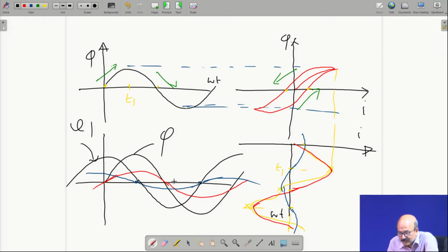One is of course the rate component, which is predominant, which is again lagging V1 by 90 degrees, but you have an in-phase component which is in phase with V1. Why has the in-phase component come up? To account for the hysteresis. V1 multiplied by I1 will be the hysteresis loss on integration. If you do it in time domain, or you just do phasor multiplication, V1 capital and I1, cos of angle theta is 0, cos theta is 1. So V1 I1 simply will give you the hysteresis loss.